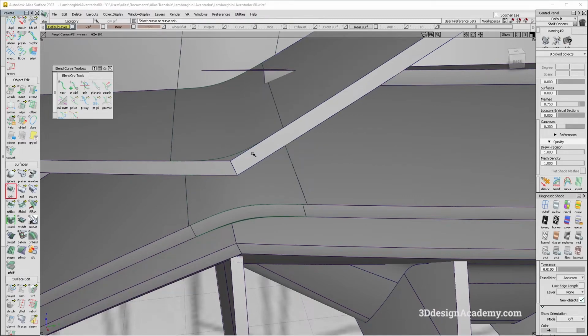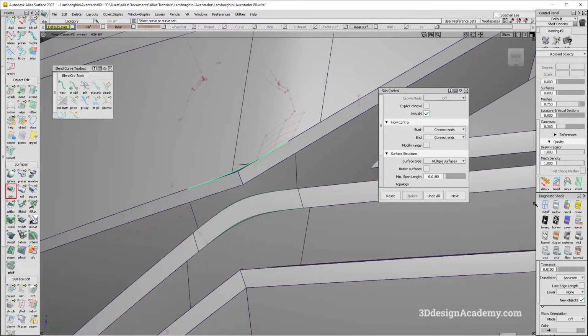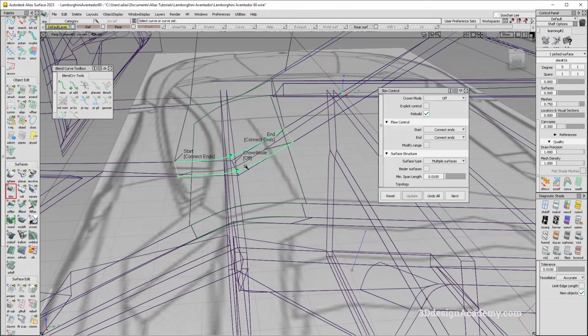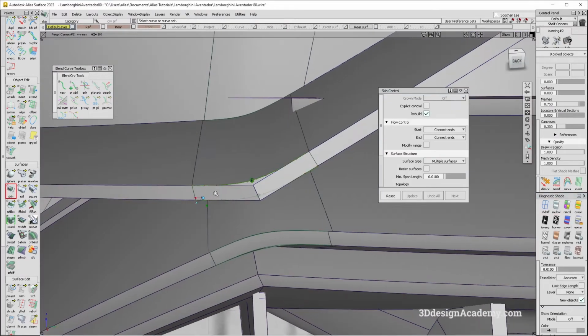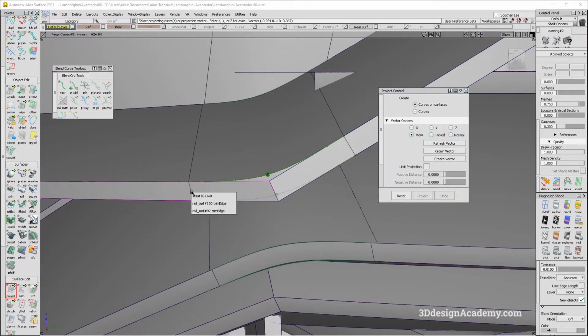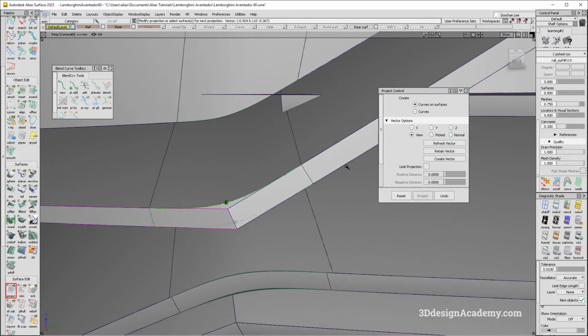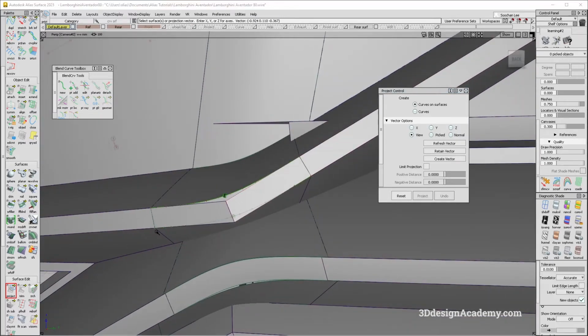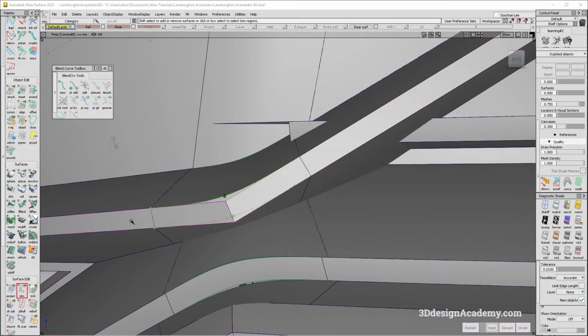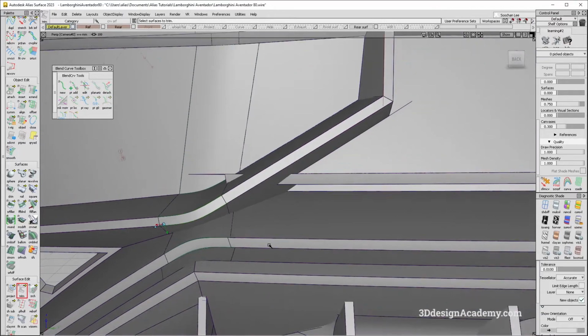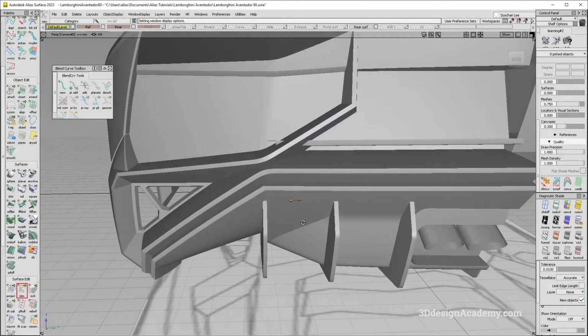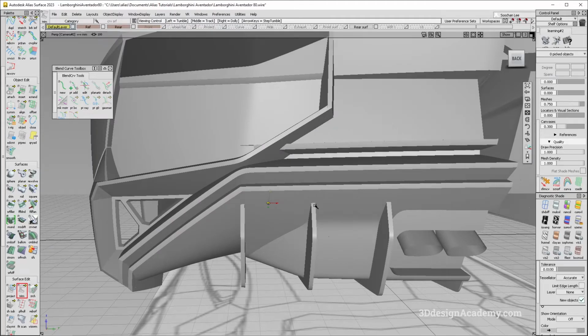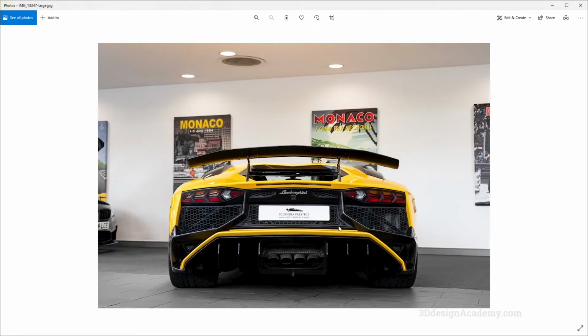So in this case, what you have to do is, right now we are not trying to clean up the fillet. What we're trying to do is just make sure that the size is appropriate for the area. So in this case, what I like to do is have a fillet here and a fillet here, and I just connect them with skin or freeform blend, and I just trim the ends so that I can roughly see if the fillet's big enough or small enough.